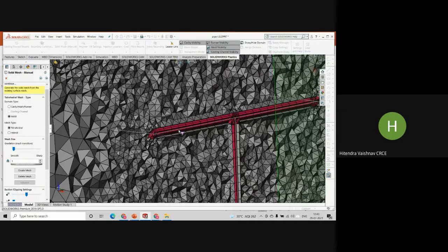So whenever people differentiate between finite element and finite volume, this is for students also, they are almost the same. But whenever volume is important for us, let's say I am analyzing some fluid flowing through a pipe, then on the pipe I have to go for surface mesh, of course, because friction plays a very important role. And inside the pipe, the fluid's outer layer, which touches the inner layer of the pipe, that side it will be hexahedron. Yeah, Prachit.